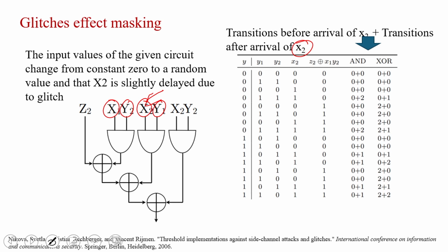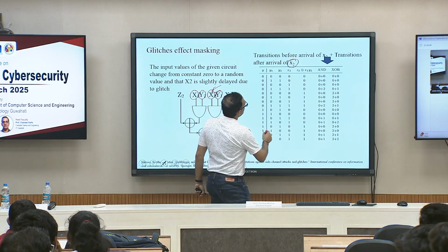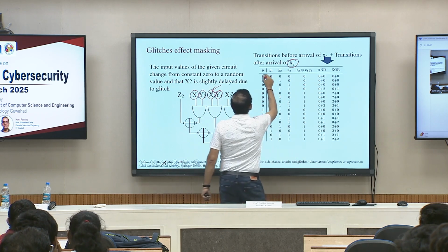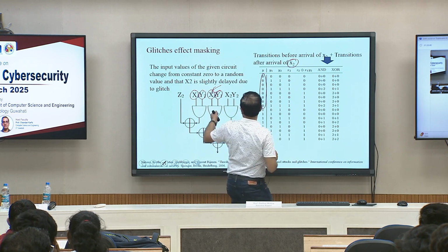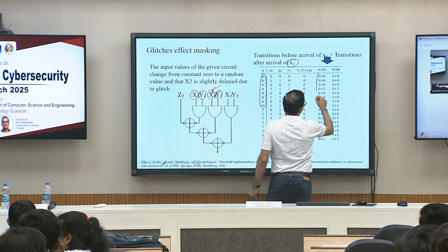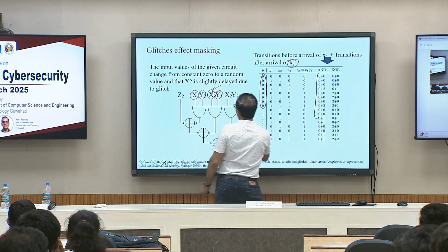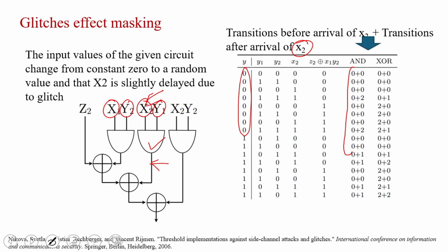Okay. And if you do a thorough analysis, they can identify that before the glitch, if the value of y was actually 0, how many times this AND operation is happening here, right. If you just probe here, how many times your value was 0 earlier and what is the next value. You can see that only in 2 occasions the value changes.